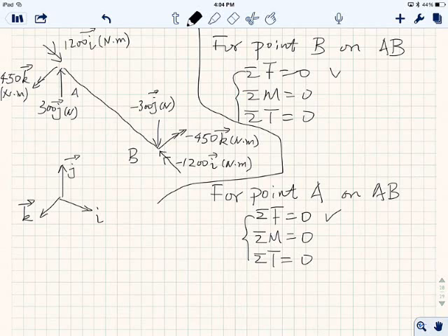There's one more thing, right? Which is the bending moment caused by the force, because AB is a cantilever beam. A is fixed, B is free. Because we sectioned it into three different members, the free body diagram is to analyze the force and moment inside each member individually, right? So in this free body diagram, A is fixed, B is free.